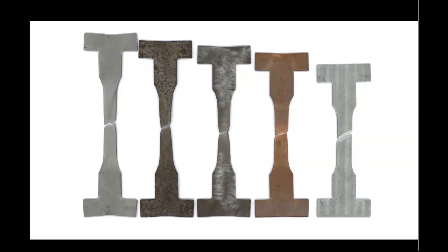So that's wrong. Option B, defects facilitate plastic deformation by enabling dislocation motion, typically lowering yield stress. This is the correct answer, okay? Because if you have a void, or if you have a point, line, or slip defect, what it basically means is that you allow grains to slide relative to each other. So yes, the connections between the grains are compromised,